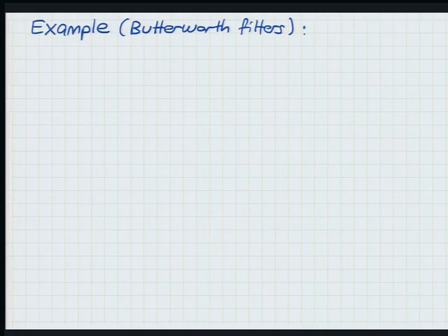All right? Well, how do I do that? If I have to first sample to filter, that defeats the purpose, right? That's the circular argument. So first I have to do an analog filter, take my continuous signal, make sure its spectrum is now bounded, it's a finite bandwidth, and then sample fast enough so that there is no aliasing. And then you can do fancier digital filters. But first you need a quick analog filter to cut off the high frequencies, right? So they remain relevant in some niche corners, analog filters. And so Butterworth filters are a very special class. They are nice and smooth.